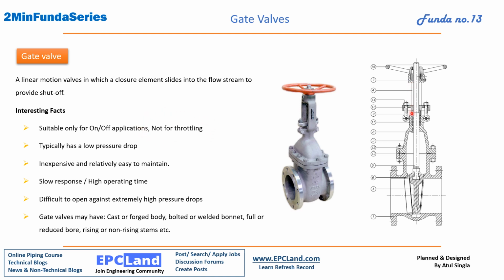Because the sliding part is there. If we shut it partially, then the flow velocity will be very high because the full opening will not be there, so it may damage the sealing where this wedge is going to rest. Okay, so to avoid that, we are not going to use this kind of valve for throttling. Typically it has a low pressure drop. Okay, this is one of the basic properties where we are going to use gate valves.